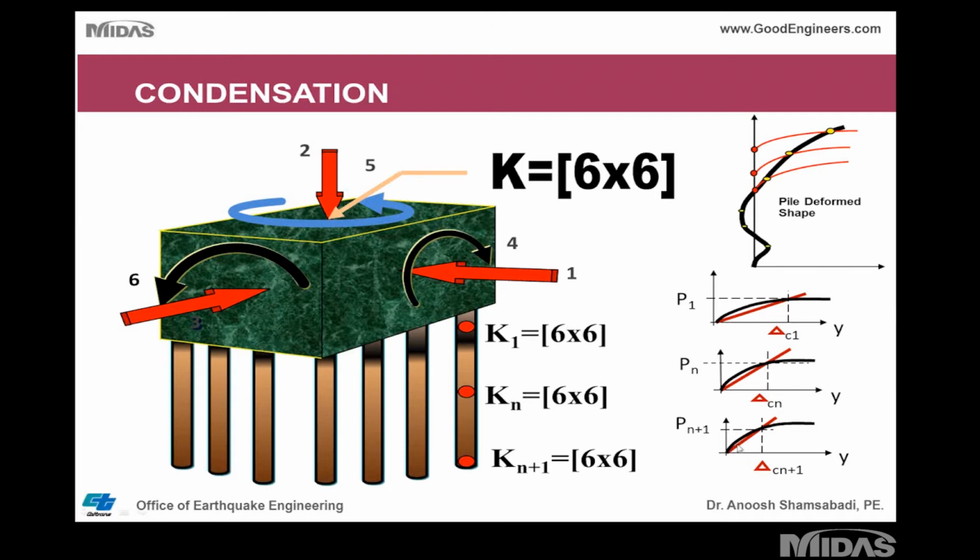And that's how you linearize, again, as a function of displacement of the piles, you linearize your springs. These nonlinear springs at displacement 1, 2, 3, for example. And then you incorporate it into your substructure model. If you do a direct model, you don't have to do this. You don't have to worry about all this. All of these nonlinear springs will be part of your foundation model, and part of the superstructure model.